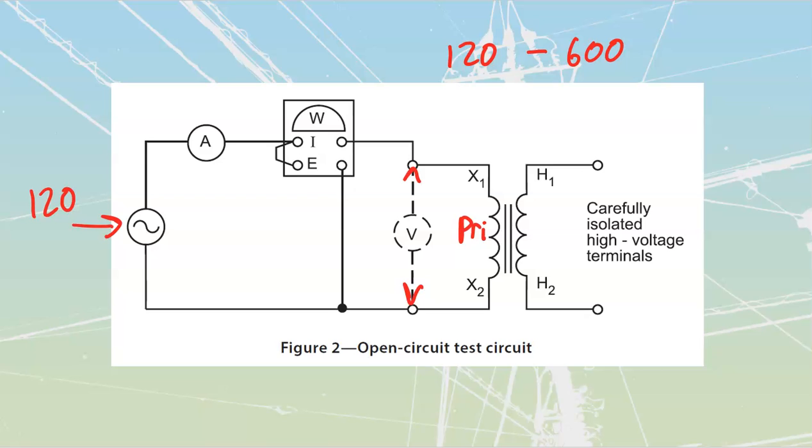Once again, for those of you that don't remember how wattmeters themselves are connected, our wattmeter has a current section, an ammeter, that is tied to a voltage section inside of here. So these two are tied together, and they're only going to display true, actual watts. They only display anything that's an in-phase type of current. With this volts and this amps over here, I can multiply those two together because they're separate, and I would get a VA off of these two. But this wattmeter measures both current and voltage at the same time, and when it does that, it only measures it as true watts.